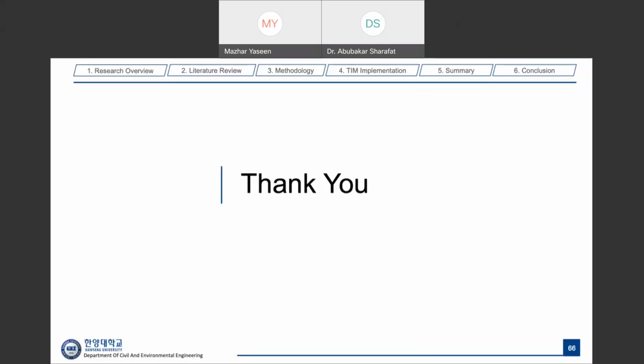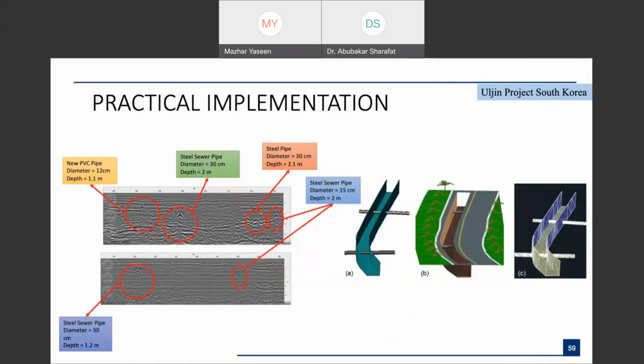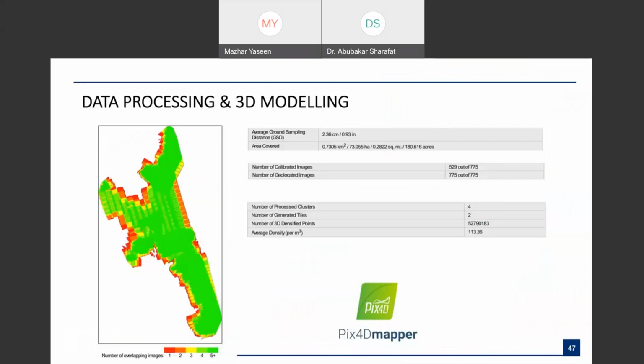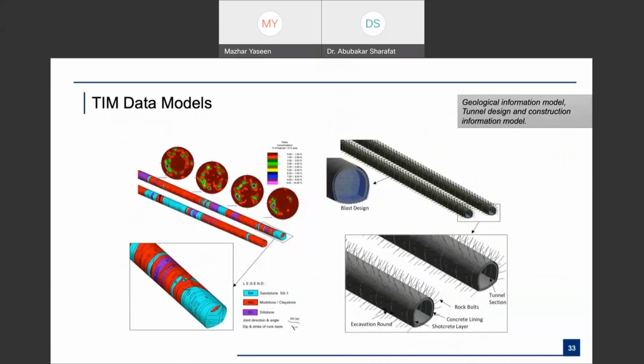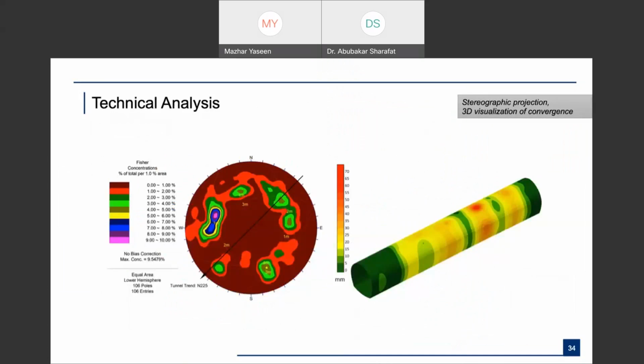The other thing is, even during construction, maybe you can have the convergence stations. I have shown you a slide in which they have the convergence data. We have done this, but we use our own Dynamo codes to develop these things. All the information that is coming, you can put it there and record it day by day. It was a colorful figure showing different types of monitoring, showing every day how much convergence there is or which part has it. Okay, next figure. In this figure, if the tunnel is operational or even during construction, the chart is showing you the maximum convergence so far since it was constructed and fully supported. You can see that the data is coming every day.